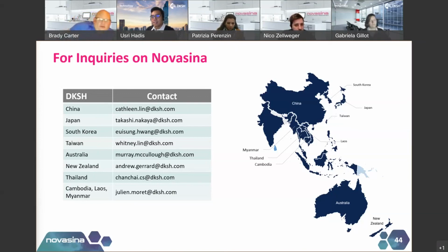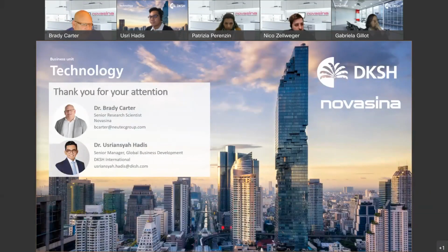Okay, so another good question. Karl Fischer tends to have a fairly high reputation within the pharmaceutical industry as being the most pure way to measure water or moisture content, and that may be true. It is meant to be more specific to water than other moisture content approaches, such as loss on drying, where things other than water can volatilize out. But even in its purer form, its purpose is to find out how much water is present. It's a concentration of water.